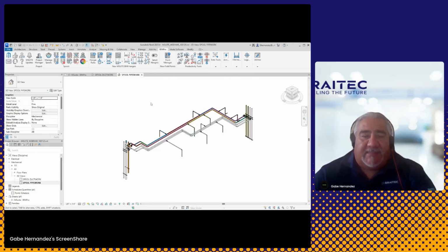And if there's certain criteria that you need to choose, turn off and on, when you create the view you want to turn things off that you're not spooling, maybe inline stuff, families. You can spool families. I'll show you that setting here in a second. But you could use the select all alike under the data tools to set up a rule to choose what you want to spool and what you don't, like I did with the round duct, and then isolate that view and then run your spools, very easily.